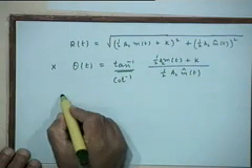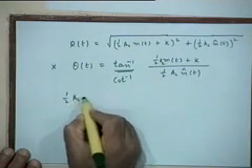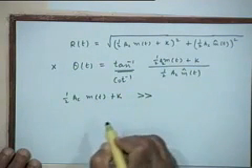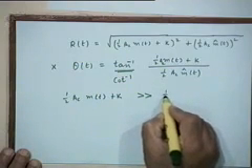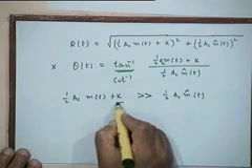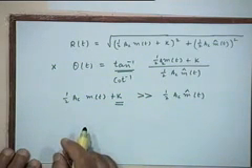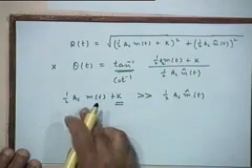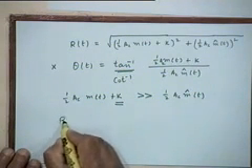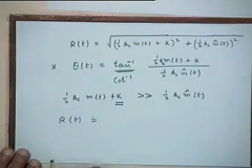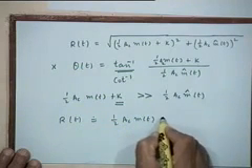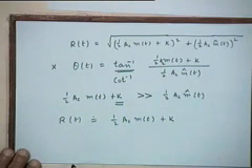so that this can be ignored in this squaring and square rooting process, right? So if we make the assumption that half A_c m(t) plus K is much greater for all time than half A_c m hat(t), which can be easily done by choosing K to be a sufficiently large constant, then we can approximate R(t) as equal to half A_c m(t) plus a constant K, right?